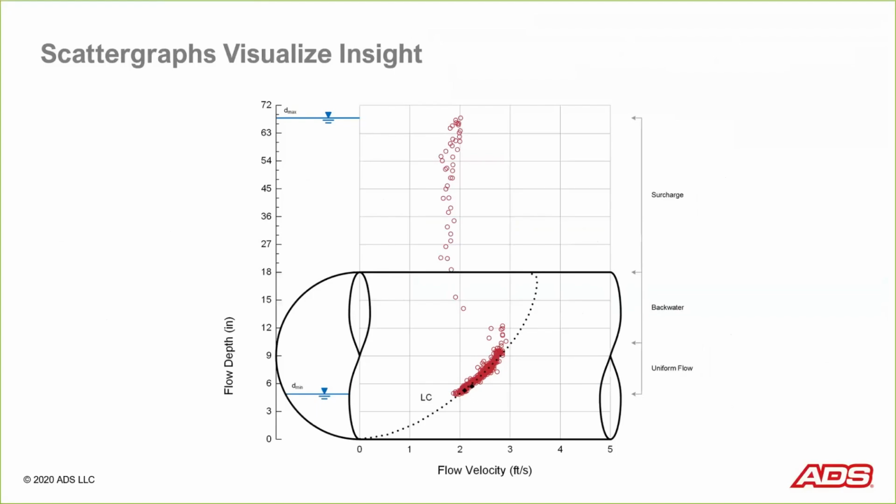Where the 2 agree is where we have uniform flow conditions. So everything above, say, about 9 inches and below, in this particular sewer, operates under uniform flow. Above that, actual conditions are deeper and slower than we expect. That's called a backwater condition, much like you would have in a lake upstream from a dam in a river. And then anything above the crown of the pipe that's flow accumulating up into the adjacent manholes, that is a surcharge condition. You can see all of that illustrated here.